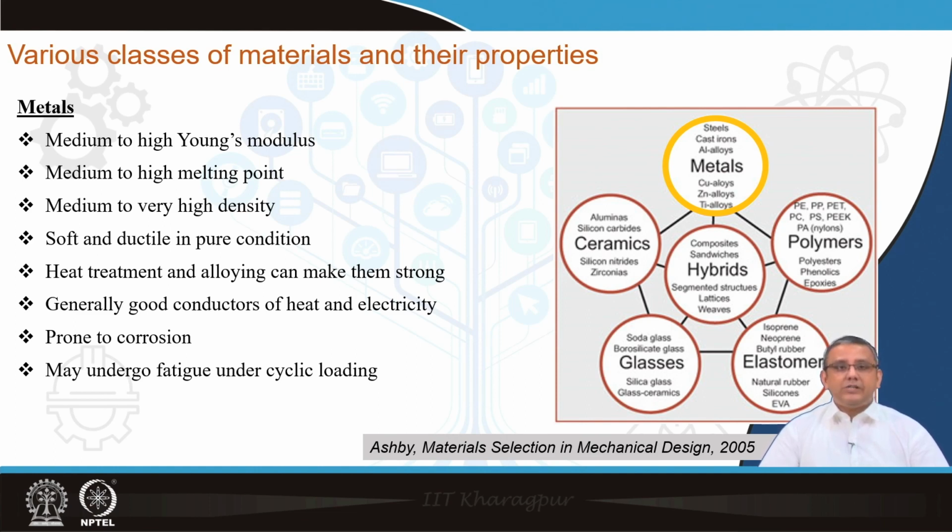Apart from that, metals also provide the possibility to optimize or enhance properties like strength, hardness, etc. by alloying. A typical example is the steels. As you know, steel is an alloy of iron and carbon. As such, iron does not have good properties, but if carbon is added in a suitable amount and a suitable heat treatment is provided, then one can develop thousands of different kinds of steels having different strength, ductility and hardness properties, and this is again extremely important for many applications of metals.